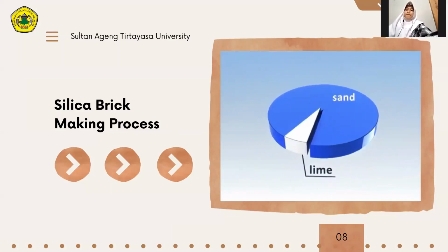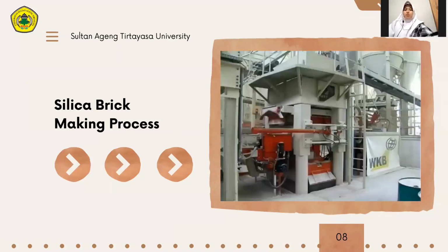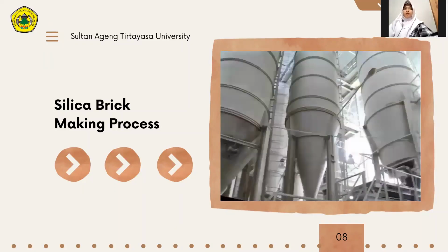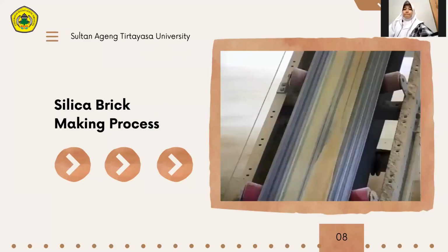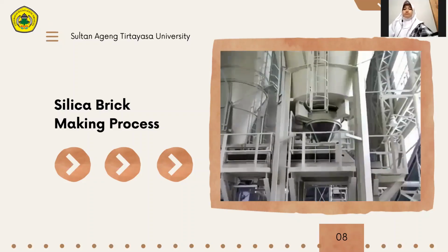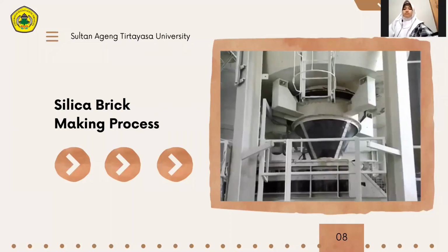Fly ash can be used as an alternative instead of sand in the production. On the sand lime brick plant silicate, all components are kept in separate storage bunkers. Depending on the production recipe, sand or fly ash and lime are weighed in weighing containers and moved to the mixer. Here, the raw materials are mixed to a homogeneous mixture in a short time.